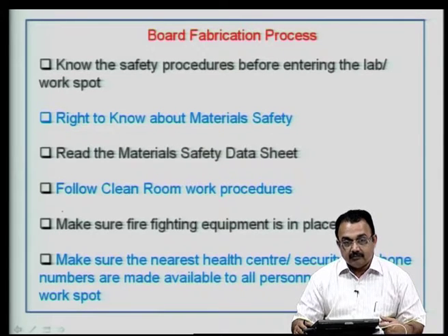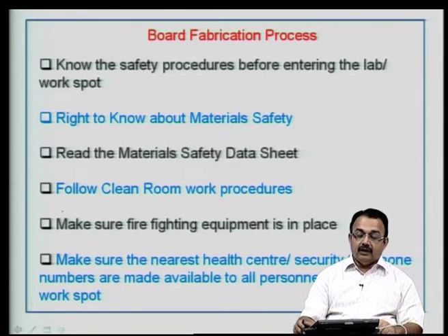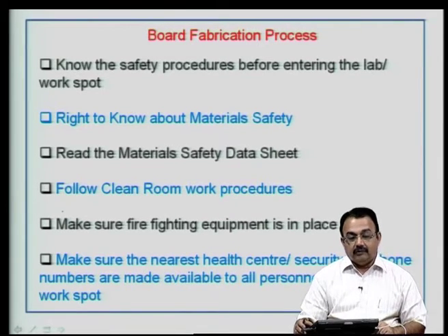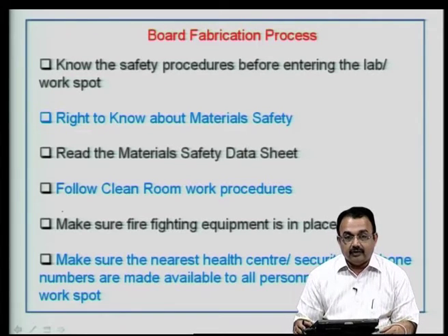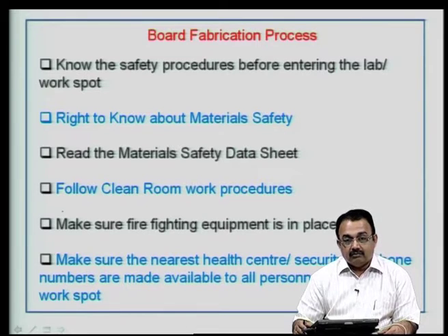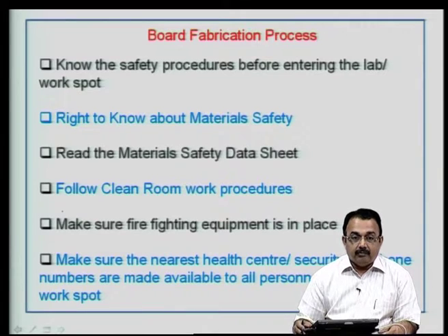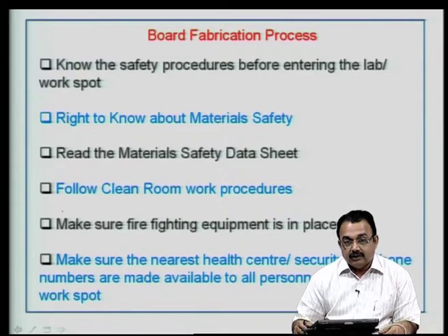Follow clean room work procedures. Clean room work procedures will again vary depending upon the classification of the clean room. We talked about clean room classifications when we talked about semiconductor manufacturing. It could be a class 10 clean room, class 100, class 1000, 10,000 and so on. Depending upon the clean room levels that you are going to work, you need to use proper gowning methodology, and proper clean room equipment needs to be in place.